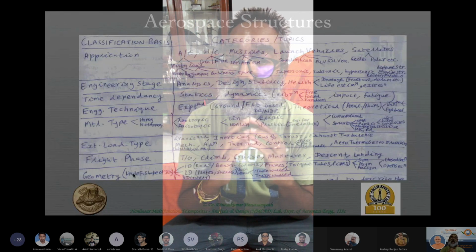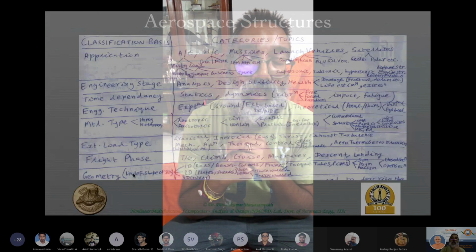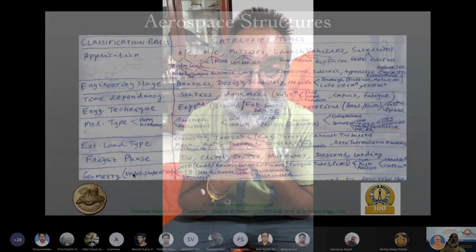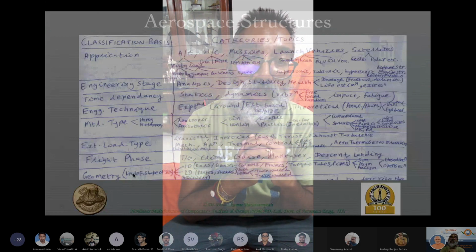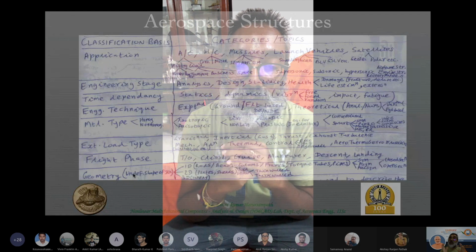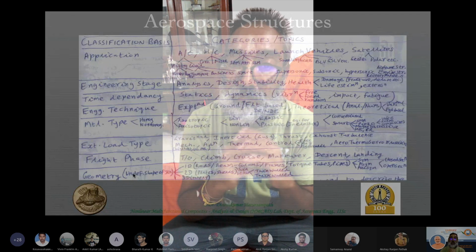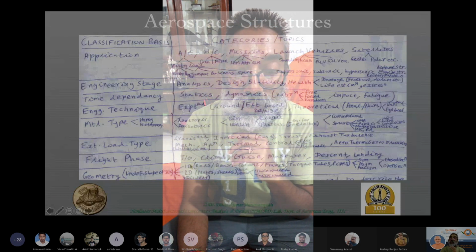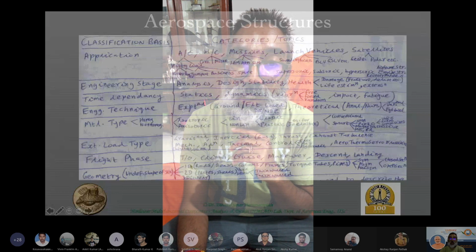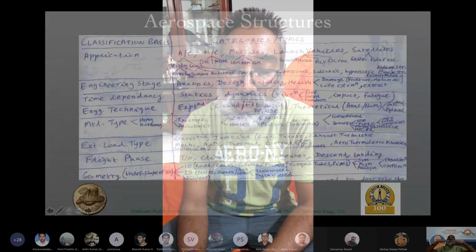But we are going into thicker and thicker composites, especially for aircraft engine applications, where we use 3D weaving techniques in order to accomplish ceramic matrix composites through chemical vapor infiltration, etc. So those kinds of processes would also deal with thicker composites where delamination, etc. is a problem. And there you may not be able to use a 1D or 2D model. You might have to go for a 3D model. So though it is rare, there are certain situations even in aircraft structures where such models are used.